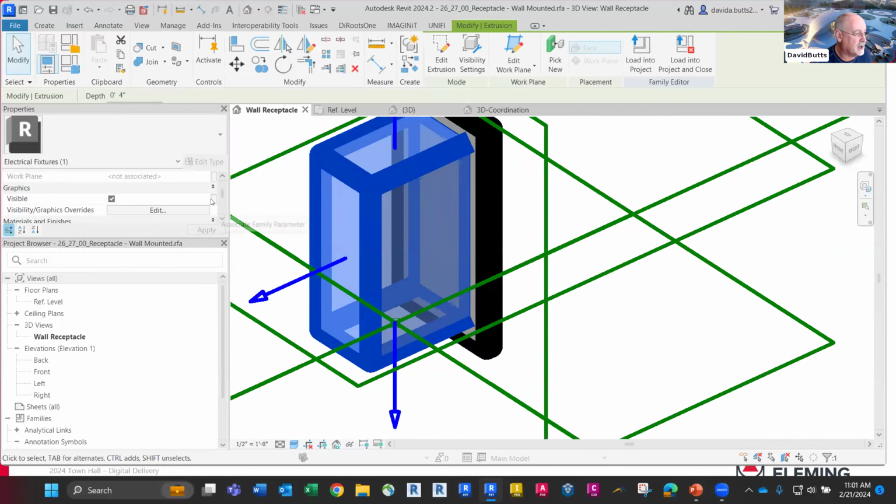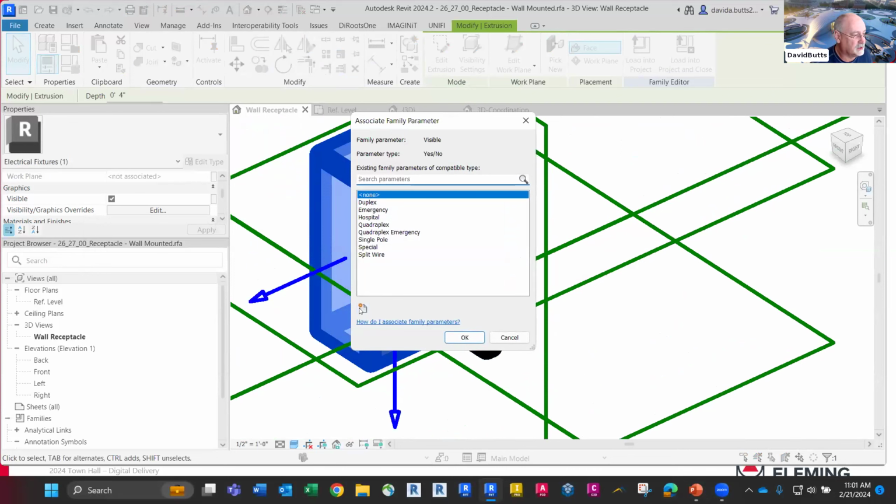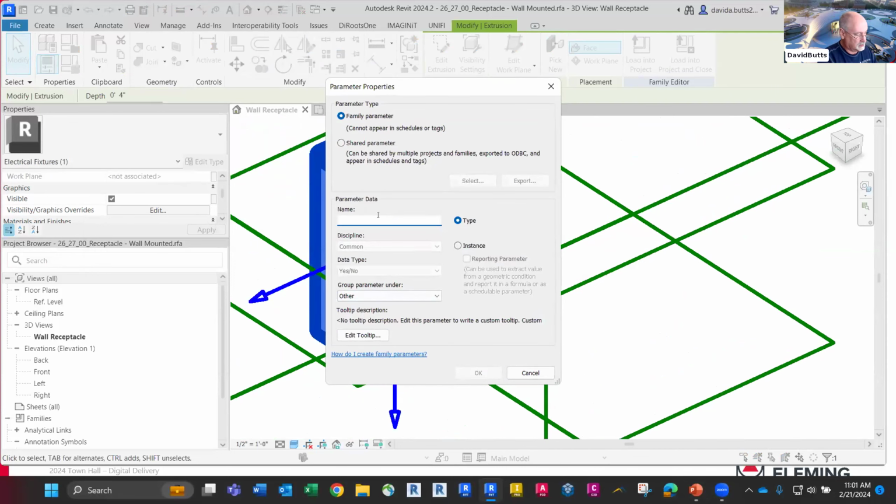If I wanted this box to be visible or not in the plan view, I actually can set up a switch here and go in and say, 3D model, and say, okay, how do I want that to appear in view? If I want each model to be unique, like I want to turn off the box and only show the faceplate, probably not something that you're going to do, but in a 3D view, if you want to limit that, and if later on you're doing a data exchange and you want to pull just faceplates out for a data library to say, I need to know how many faceplates I'm having in a project, think down the road about how you would do that.